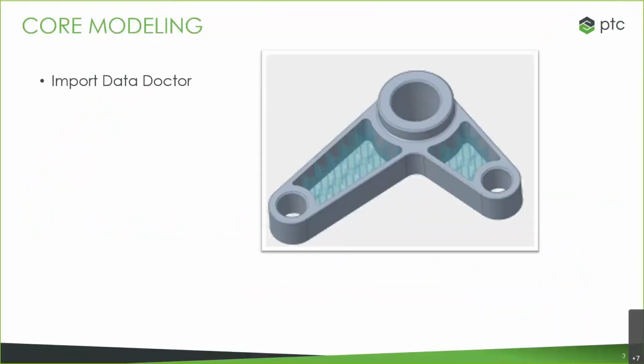So first, we have improvements to the import data doctor. If you're going to be bringing in non-native geometry, we now have support for MultiBody. And that's something that we're going to get into talking a bit with that MultiBody design. And specifically with the import data doctor, there's now a troubleshooter looking for things like open quilts and how we get through and fix those.